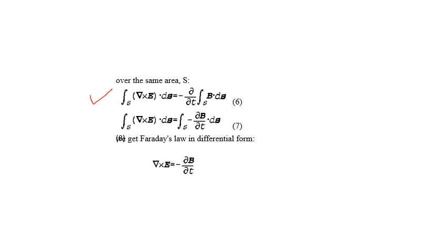And this is called the Faraday law in differential form. So again you can revise this, but it's very easy. First take the Faraday law in integral form, then apply Stokes theorem to convert the line integral to a surface integral, then convert your flux in terms of magnetic field, again as a surface integral. If both are surface integrals, you will get this equation. This gives the idea of Faraday law in differential form.